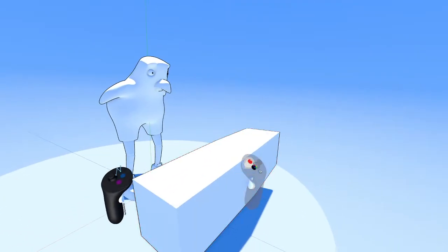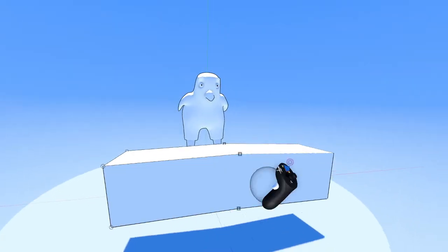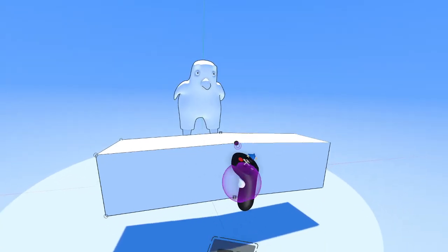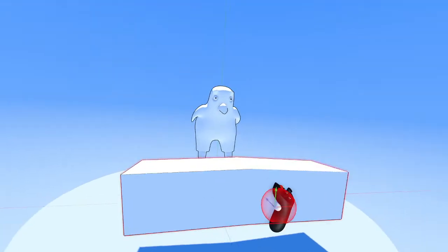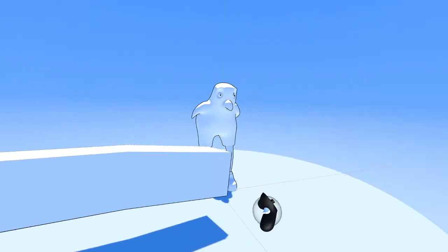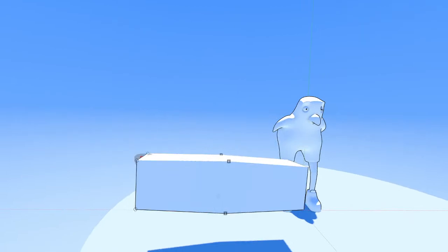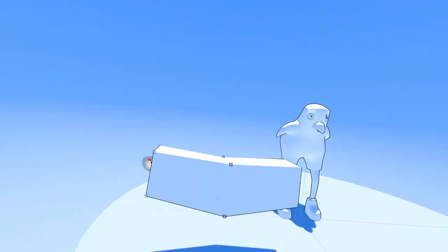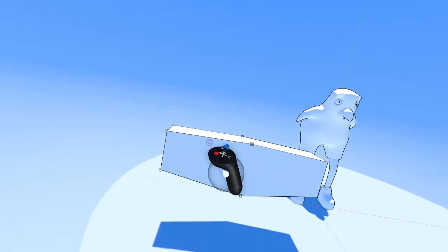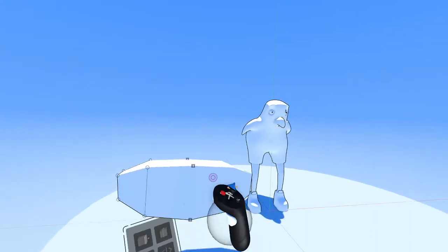But the nice thing about sub-D objects is, I took these cubes, converted them to sub-D, and connected them across the mirror plane, and we can see that with that icon change there. Sub-D objects actually do retain their mirror. So if I move it off of Y and Z, you'll see by putting it in edit mode, it still retains its mirror. So sub-D objects are the only objects that actually do that in Gravity Sketch as of right now.